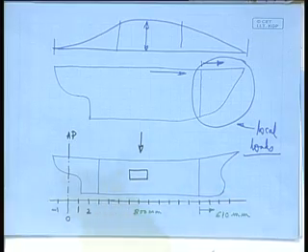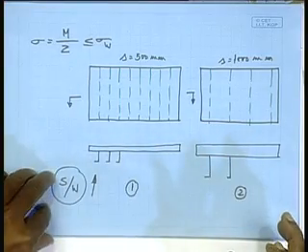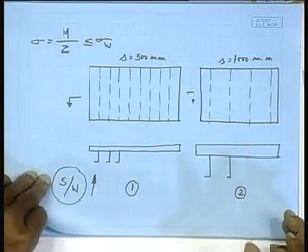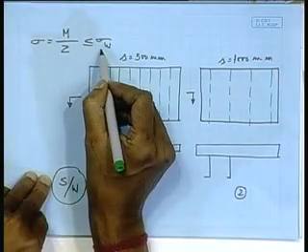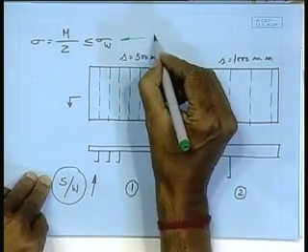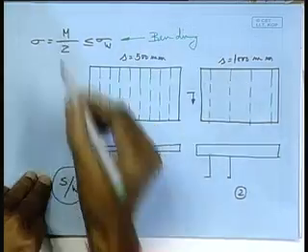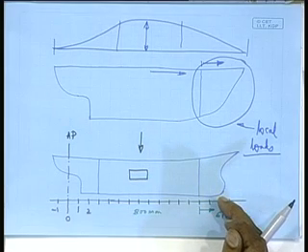What does that mean? I am putting closely spaced stiffeners. One implication is that it will become heavier, let it be, but additionally stronger rather. There I am not only looking into bending, essentially due to the bending moment, but here I am looking for the local loads.